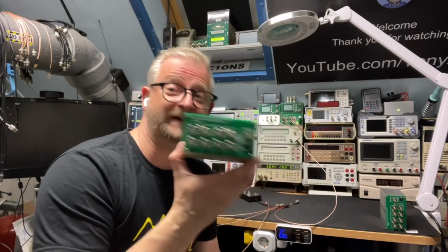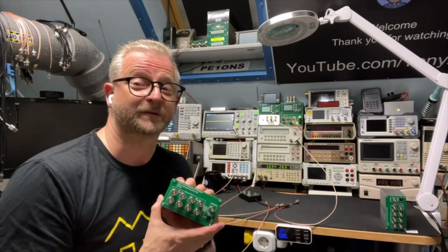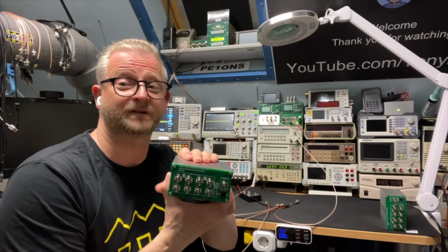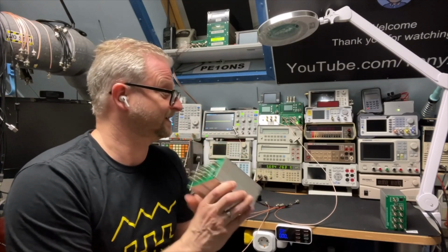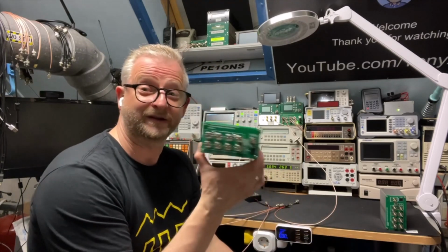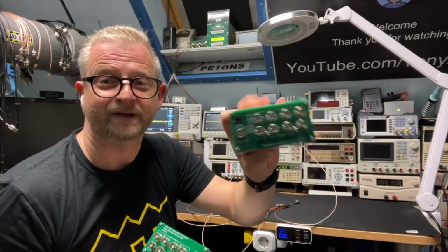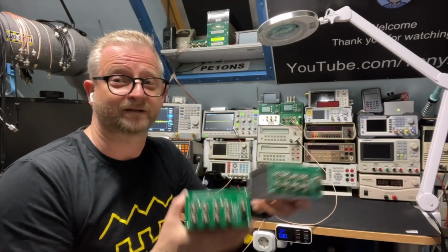So you can see that this special 10 megahertz distribution amplifier really is a lot cleaner, but you pay more for this because it's already around 90, and I think with the internal oscillator it's already 100, but it is a lot cleaner, but only usable for 10 megahertz. Well, this one was cheaper, and you can use from 0 to 200 megahertz, so that is your choice.